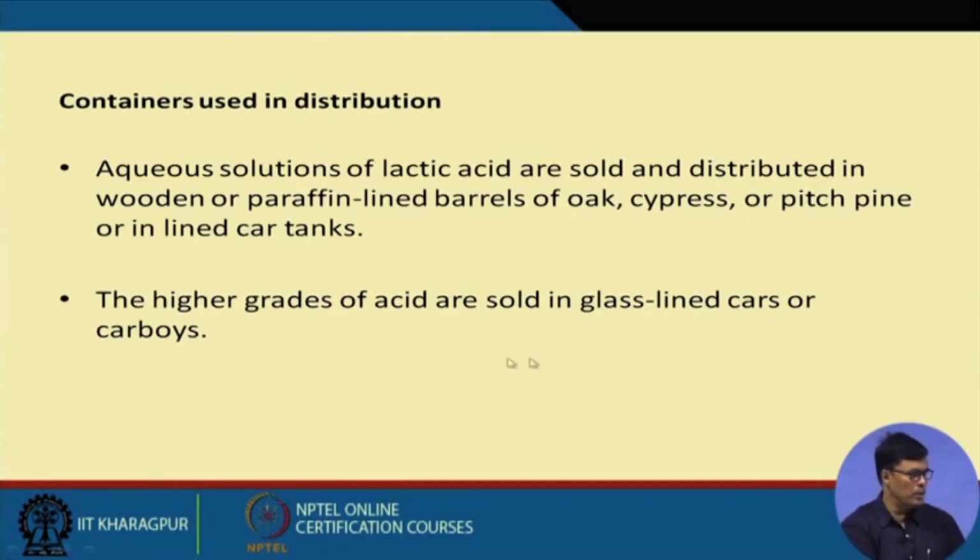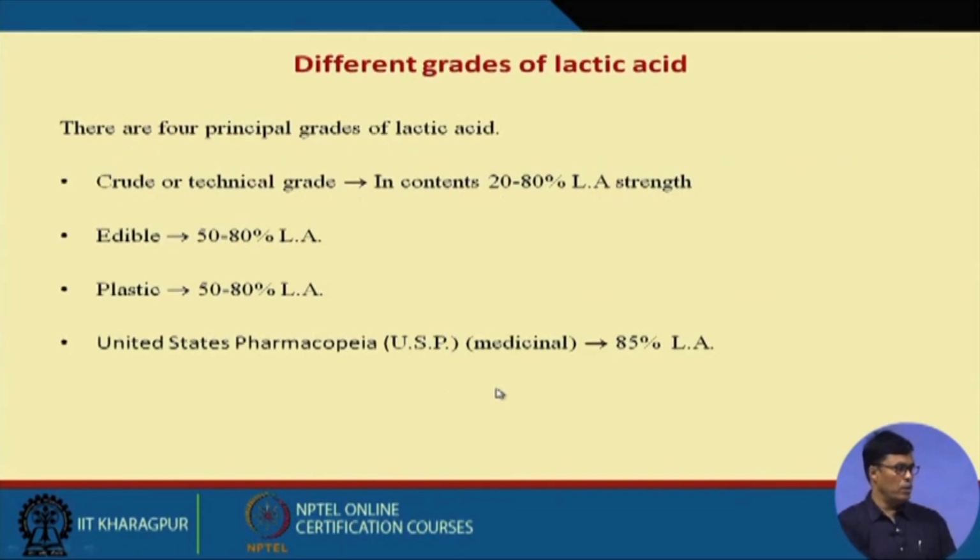Some glass lined materials can also be used for transferring this material. Then it will not affect the material of construction to a great extent. Otherwise, the material will be affected by the lactic acid. So, this is very important.